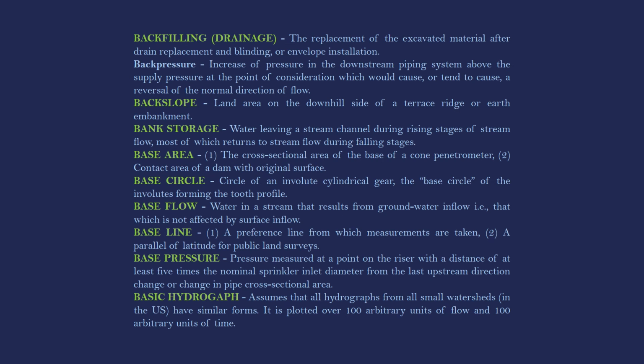Backfilling drainage. The replacement of the excavated material after drain replacement and blinding, or envelope installation. Backpressure. Increase of pressure in the downstream piping system above the supply pressure at the point of consideration which would cause, or tend to cause, a reversal of the normal direction of flow. Backslope. Land area on the downhill side of a terrace, ridge, or earth embankment.